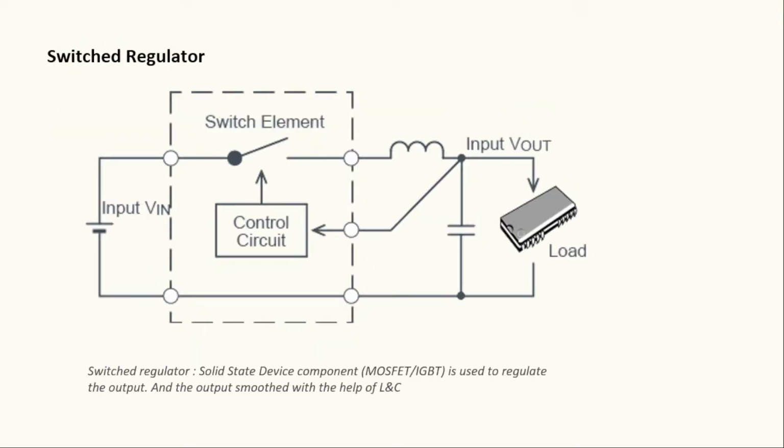See, in that converter, for example, in our circuit we have a switch, and the switch does the converting. You just assume it's a buck converter, right? We have the input, and with this input we have one switch, one inductor and one capacitor, and then the load output.